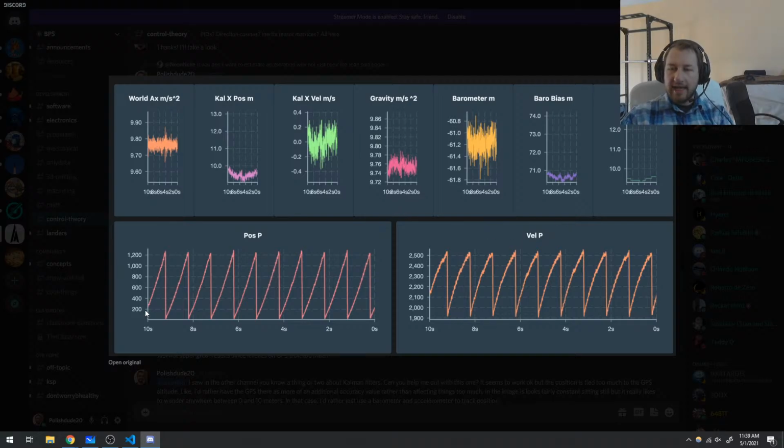And so you can see what's happening is, as time goes by, the uncertainty of my position gets higher and higher until the GPS comes in at every second, and it brings the uncertainty down, right? Because the GPS tells me, no, your actual position is this. And then as we keep predicting and updating with the barometer and stuff, the uncertainty keeps rising, and the GPS comes in and says, no, this is the actual position.